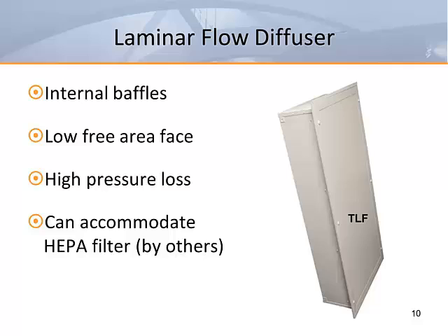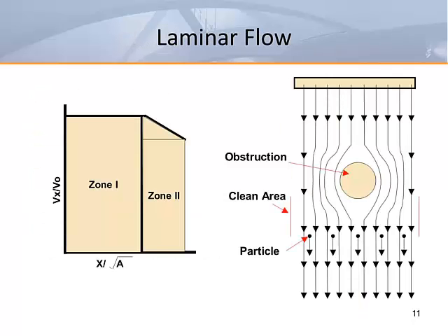While I would recommend that a HEPA filter be located in the supply air duct ahead of the outlet to allow servicing the unit without contaminating the operating room, the HEPA filter can be installed inside the laminar flow diffuser for servicing through the face of the unit. Non-aspirating outlets show little change in velocity, placing them in Zone 1 throw category.